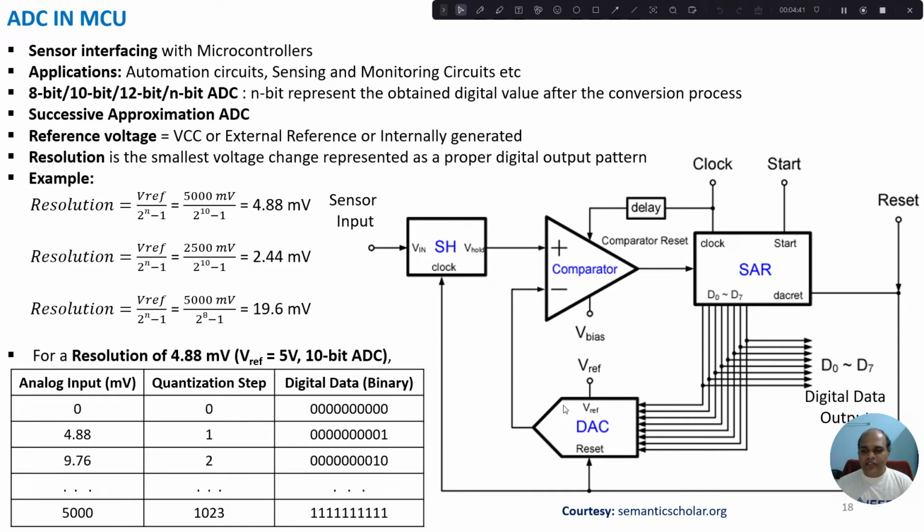First, let us assume that some value is given by the SAR register and the DAC produces a corresponding output voltage. This voltage is compared with the input voltage. If there is a mismatch, then the next entry in the SAR register will be given as an input to the DAC. This happens until the comparator produces an equal result.